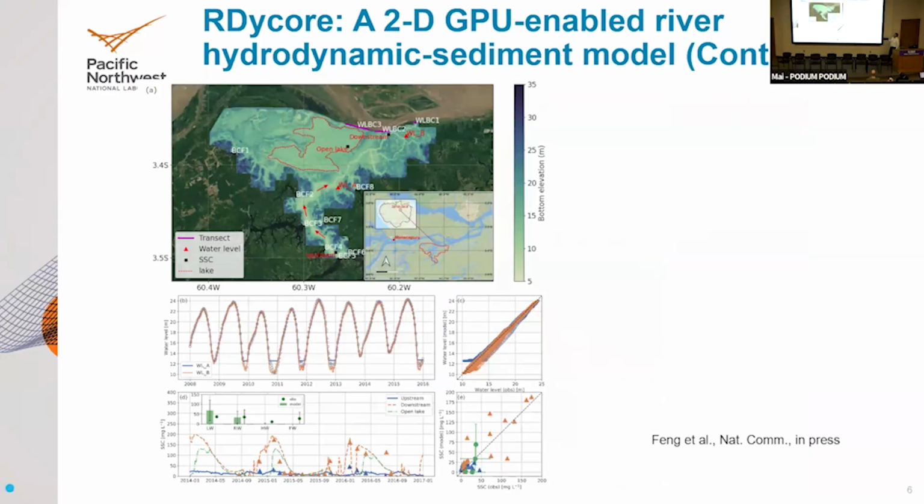In our model, hydrodynamics and sediment dynamics are closely coupled. Specifically, the sediment transport is driven by the simulated water depth and velocity from the hydrodynamic module, and at every time step, the surface elevation of each grid cell is adjusted according to the estimated sediment erosion and deposition. On the other hand, the change of surface elevation in the grid cells will impact the simulation of hydrodynamics.